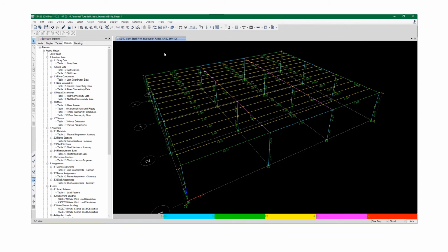So with that, we'll put it to an end. Again, like I said, our deflection issue is related to our shells and the meshing, not affecting here. Sometimes you don't even need to model that mesh if it creates too much of a problem. You can put some of these forces directly, and that helps. But it's important to model it sometimes. It gives additional stiffness to the structure, so it's not a bad thing, but it can be troublesome, and you have to kind of treat it with kid gloves.